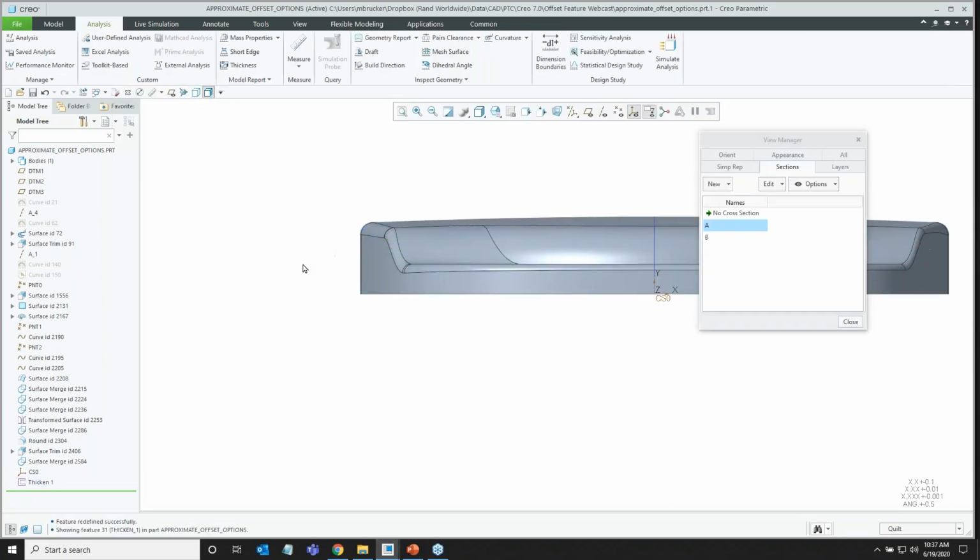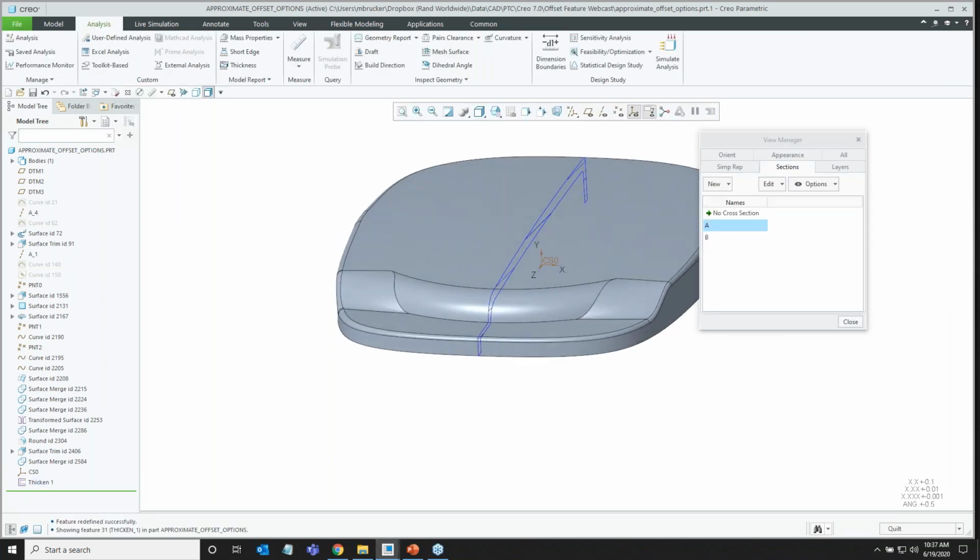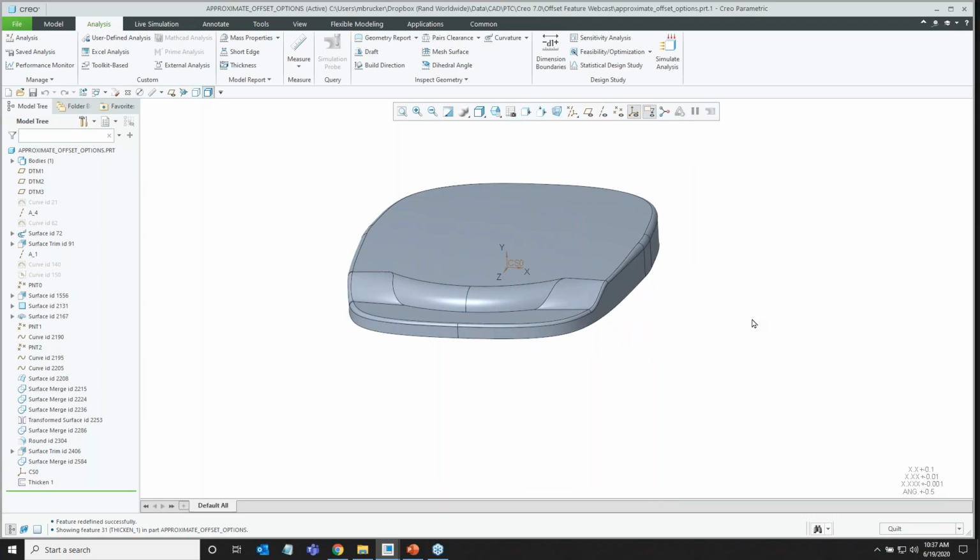And finally, I was able to offset by more than the wall thickness without getting a failure or that beveled surface. That's really the order in which you want to try the offset. Let it default to the normal to surface offset where you get the true perfect offset. If that doesn't work, try the automatic fit. If that works, great. Creo automatically fixed your problem. If it didn't, then you might go to the controlled fit where you can ask the computer not to translate in certain directions. So that was the standard offset.